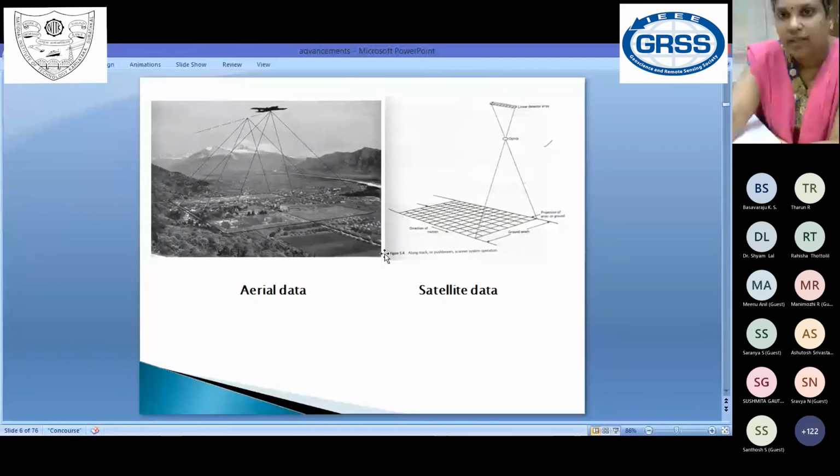One more advantage of UAV is that you can fly multispectral, thermal, LiDAR, and for aerial we have hyperspectral too. But in the case of an optical satellite, you can get only that data; multispectral and optical will be the same. With SAR and similar satellites, you will have only microwave images. But with aerial data or UAV, you can put the particular sensor on that platform and take the photography.